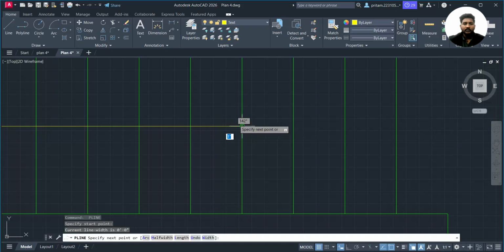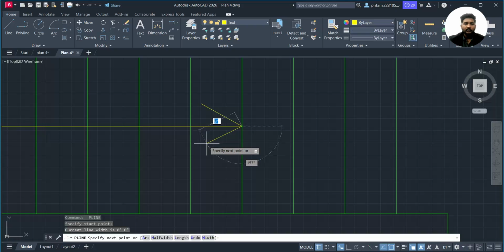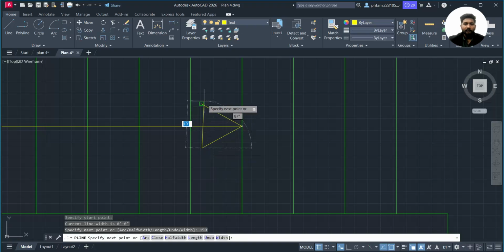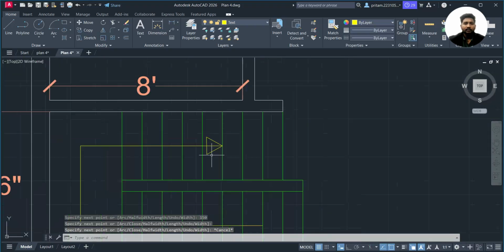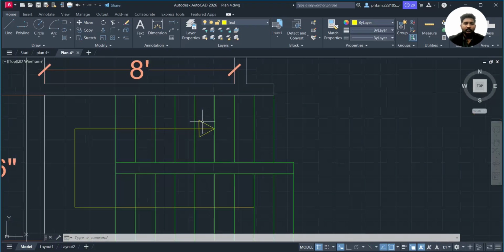Once again press enter, or type space. We will be making it in the form of the 30 degree, and the 9 inch. Escape it once again, just make it as the 30 degree. You can just place here the 9 inch, then tab here, and you can place the angle as 150. Enter. You can see that it has been added perfectly. Just choose this part, and you can see that all the dimensions are now perfectly added. Okay, this part has been completely added.